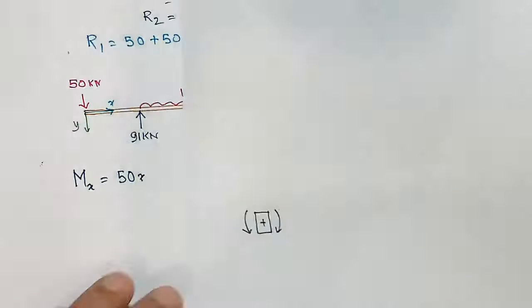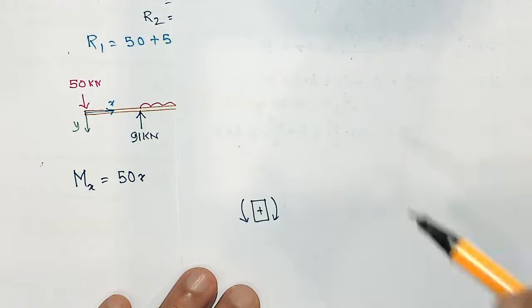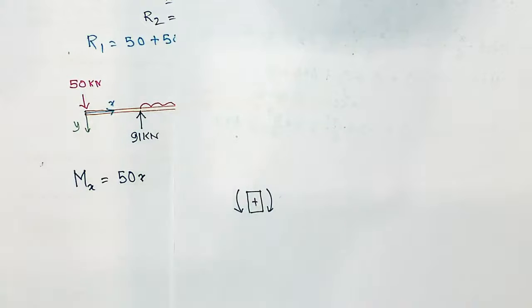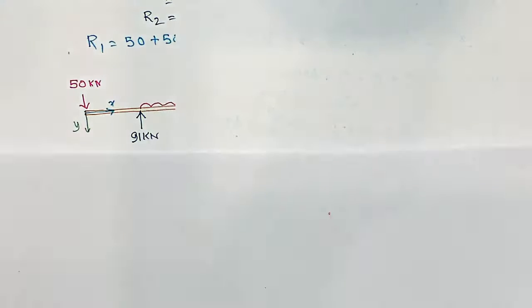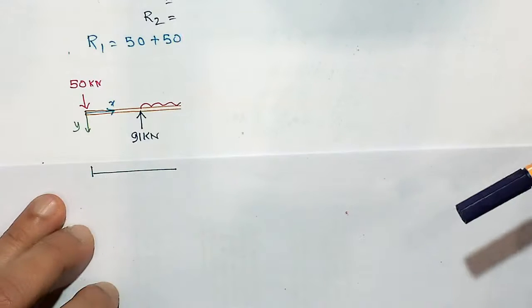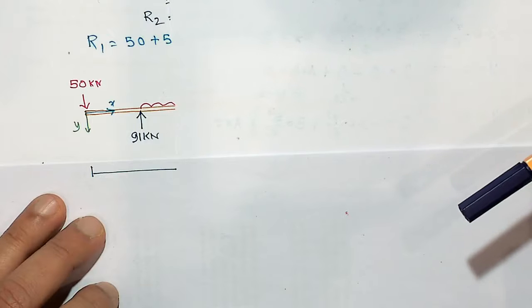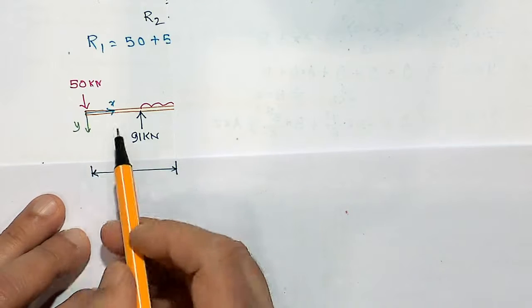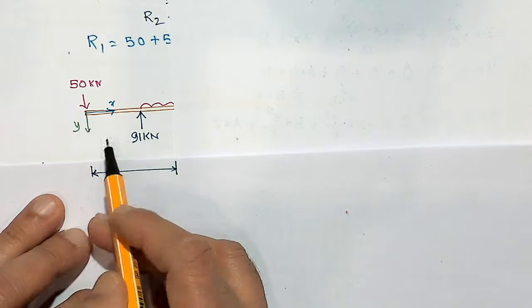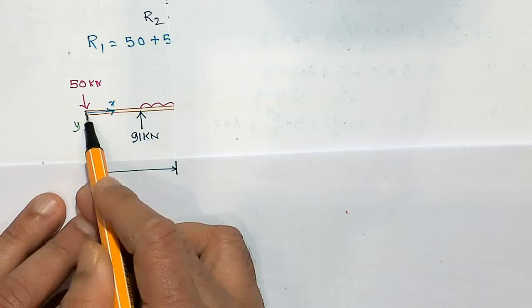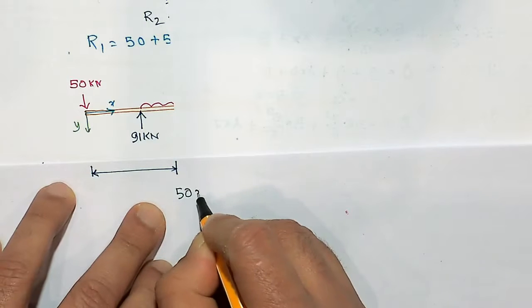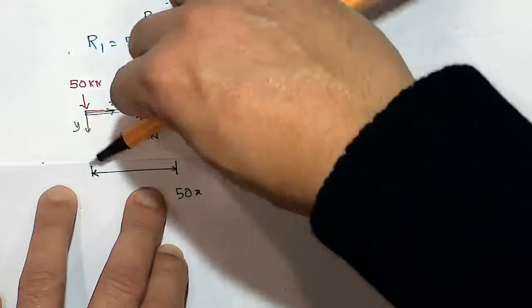Now I come to here. Now x is this much distance. This distance is x now. So I have now got 3 forces instead of 1. I have the force due to 50, so that would be 50 times x. That would be a positive moment about this.